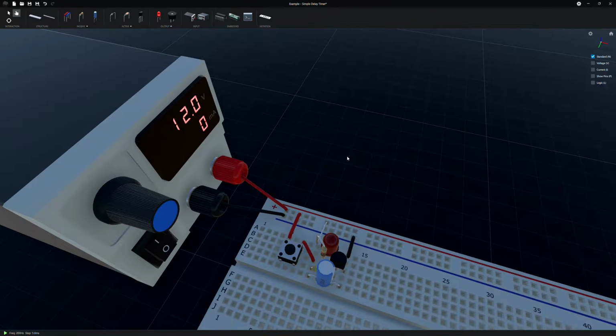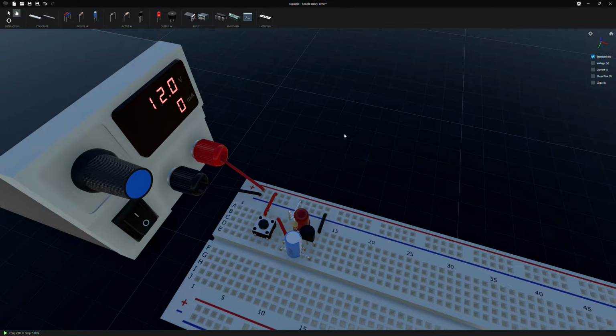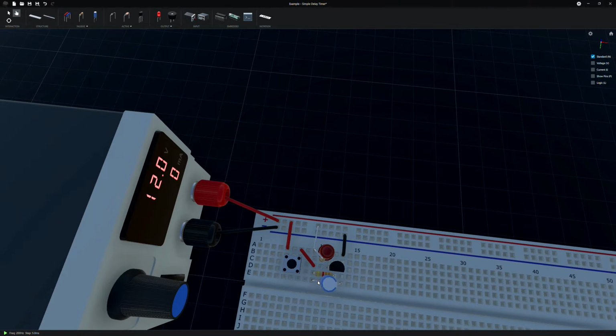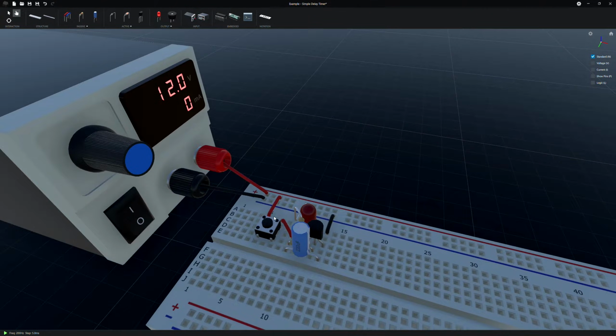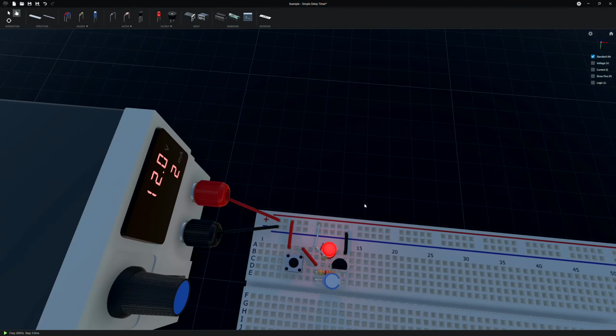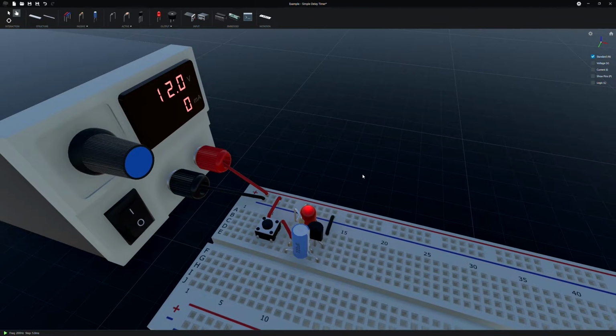And the page has a full description of how the circuit works, but basically we're just turning on the transistor and this resistor capacitor network right here charges up the capacitor, and then that capacitor discharges, keeps the transistor on for a little while until it eventually shuts off. So real basic circuit, and of course you can change the values of the resistor or the capacitor or both to get different delays. Nice and simple.